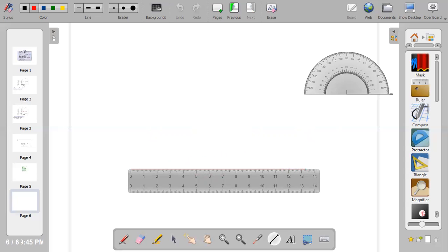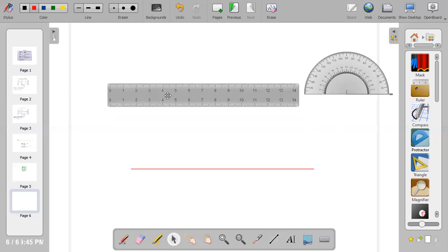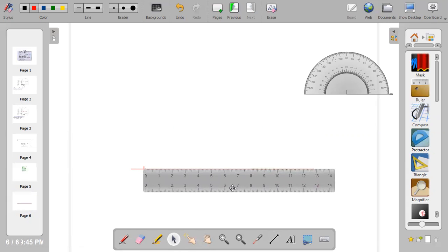Before you draw the 8 centimeter, you first bring out the natural ground level using a thin line. Don't forget, it is called the NGL. After you have drawn the NGL, the next thing is to pick a point on the thin line where you are going to start bringing out the width. Then from that point, you can easily measure out the width of the building, which is 8 centimeters. Mark out your 8 centimeters.